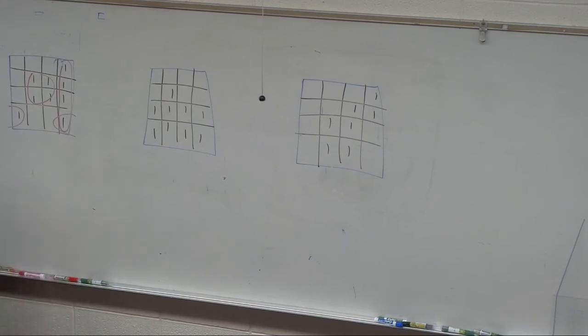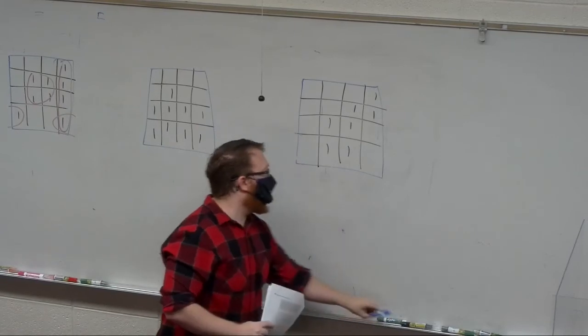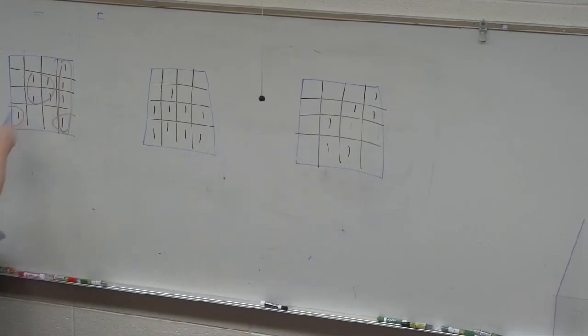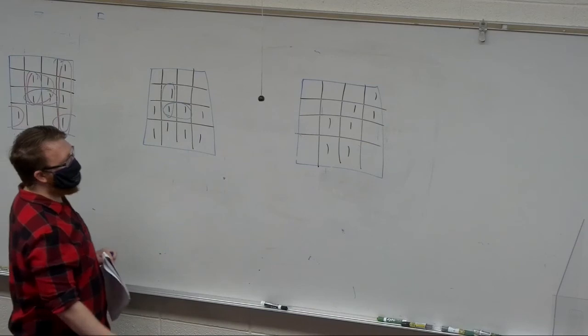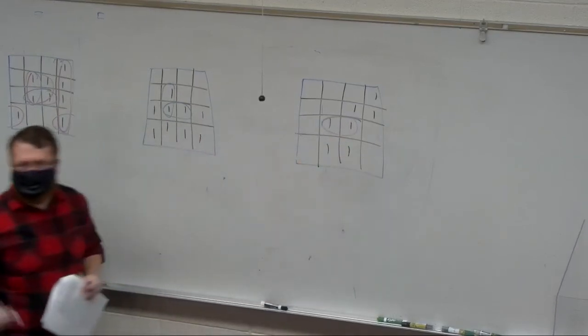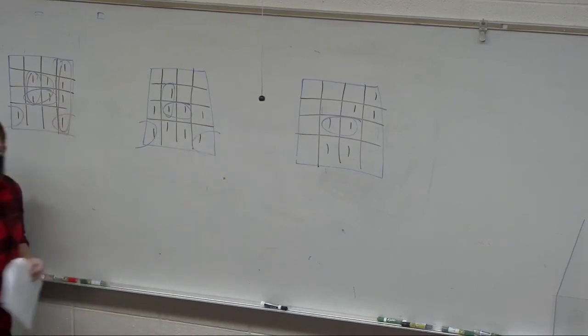But for a PLA, because I want to share these ANDed terms, what I'm actually going to do is start looking at circles that I can make in all of them, or at least in 2 of them. So instead of these 4, it's actually more useful to make this circle and that circle separately, because shared terms, right? And even over here, another shared term. So I'm now minimizing my AND gates. Similarly, this wraparound is actually really good because it's a shared term.